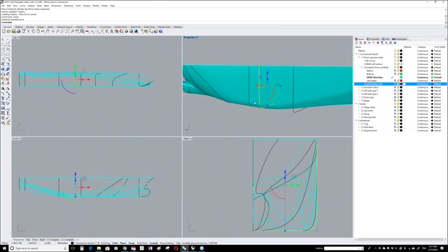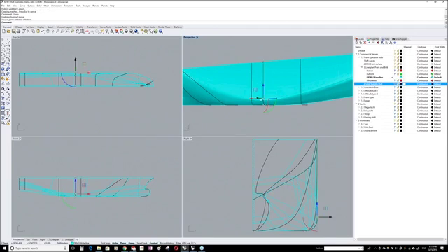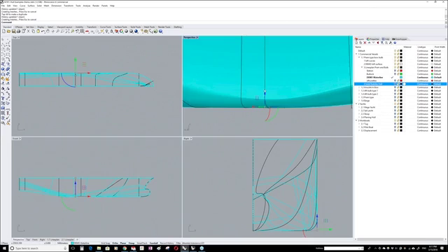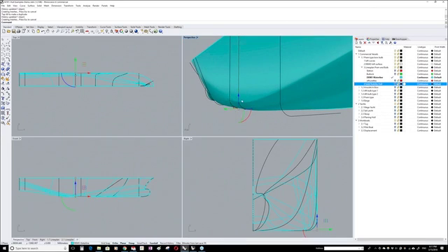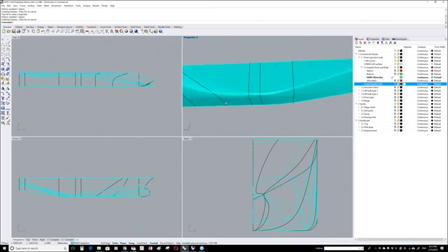It's the same with control points. When I teach students, a lot of them drag a lot with the control points, and at a certain point they don't know the order anymore, and that is something you should take care of. So what I did now is very wrong, because this control point was above the other one, and if it's twisted, you can hardly see it. There are commands in Rhino to check the order of the control points, but try to avoid it. That's something you should look at.